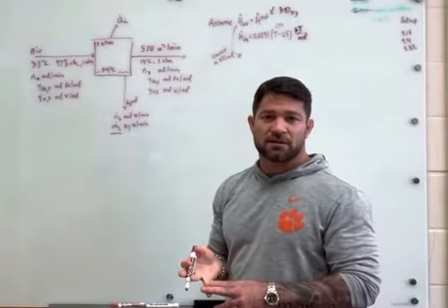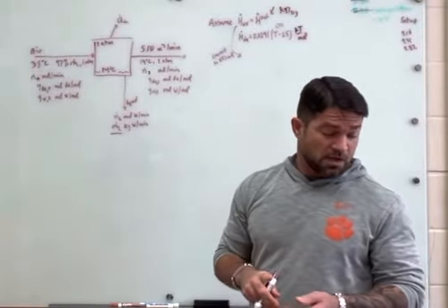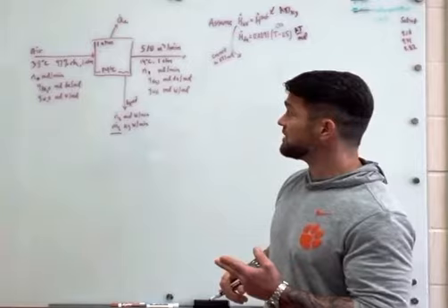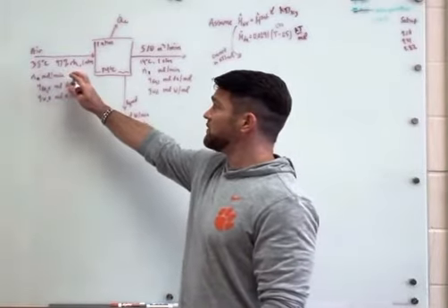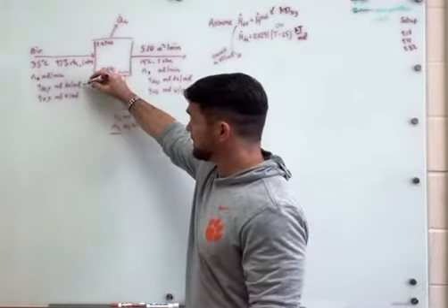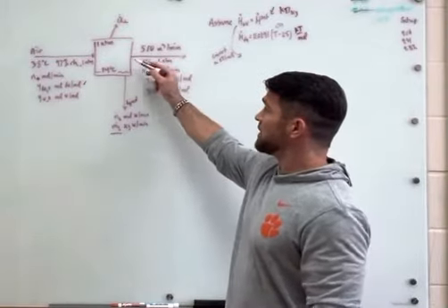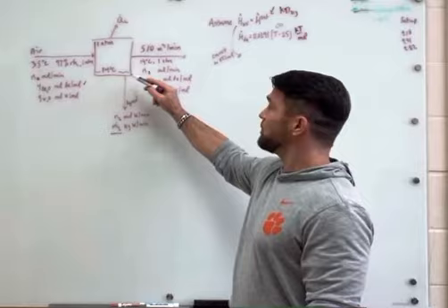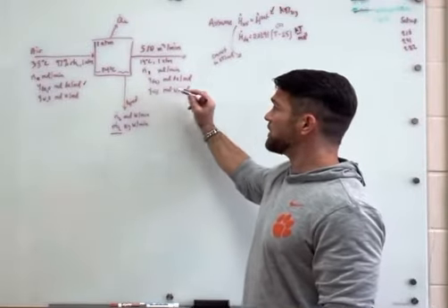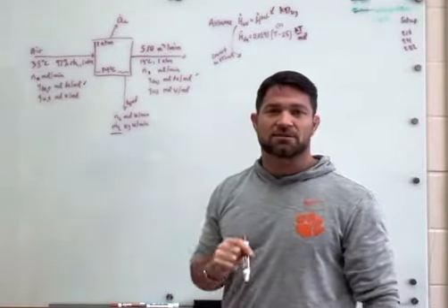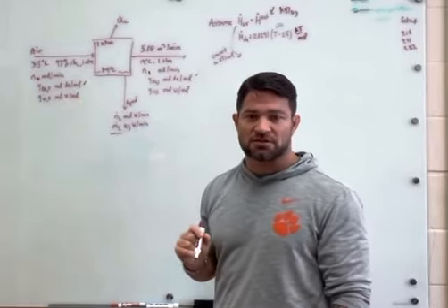There's a variety of things I'm going to need to do for this problem. First, I'm going to use the definitions of relative humidity and the temperature to calculate these mole fractions. Because we have vapor in contact with a liquid, we know the water in the stream coming out is saturated, so I can use that to determine these mole fractions.